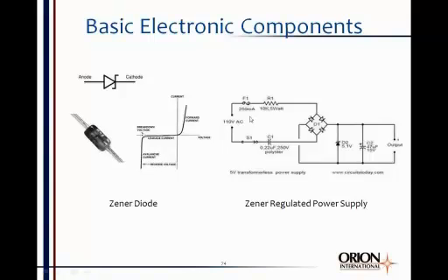And over here on the right, I wanted to look at a Zener regulated power supply. You could build this and it would work pretty well as a regulated power supply. It doesn't require a transformer to have 110 volt AC to plug in the wall and get about a 5 volt output. Okay, you can do that without a transformer using this little regulated power supply. So let's see schematically what's going on. We've got 110 volts of AC power applied through a fuse, through a 5-watt resistor. That's the guy that drops a lot of the voltage right there. Okay, it's a 10 k ohm, 5-watt resistor.